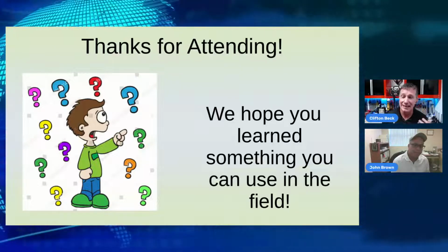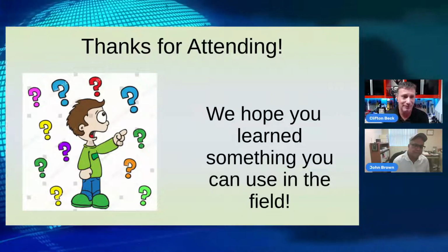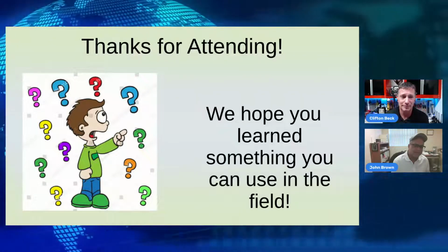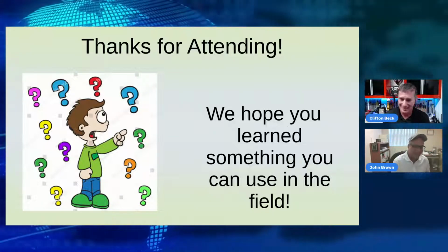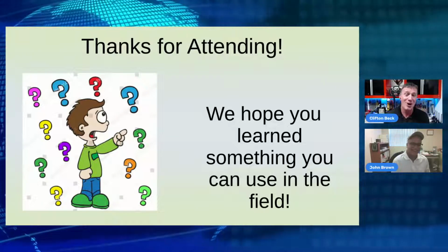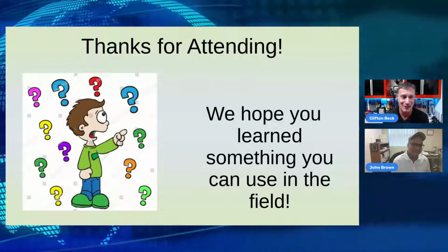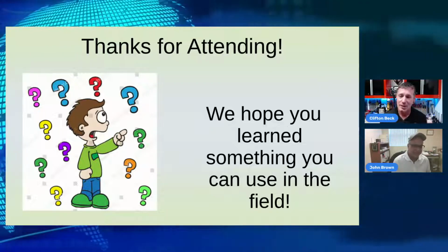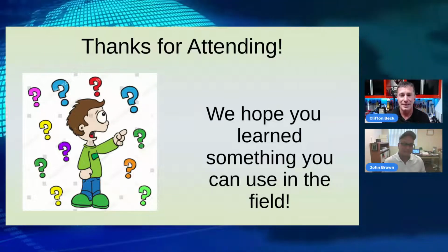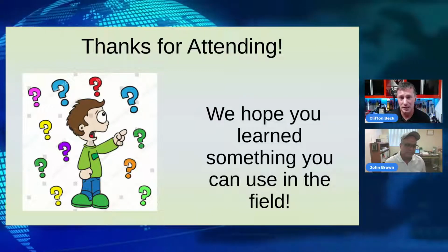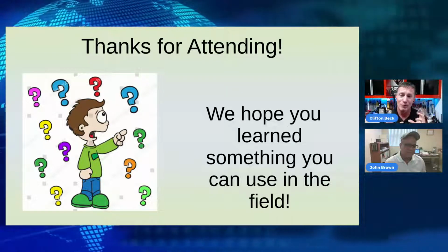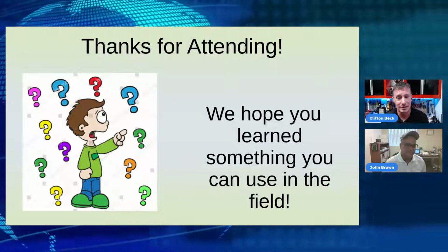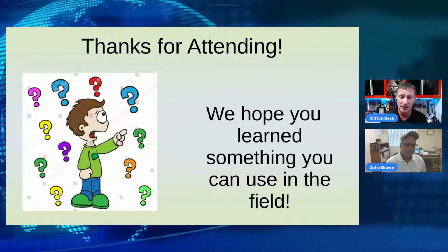If we look at a telephone repair technician 30 years ago working on the same RS-485 platform, his most important tool, the voltmeter. If we talk to a computer technician working on an Ethernet connection running on RS-485 platform, what is his most important tool? His meters. Voltmeter. So in our industry, we follow the exact same protocol. We have a 5-volt DC communicating protocol. If we know what the voltages are supposed to be, you will be successful at figuring out why things aren't functioning properly. And that has been the biggest complaint of technicians.